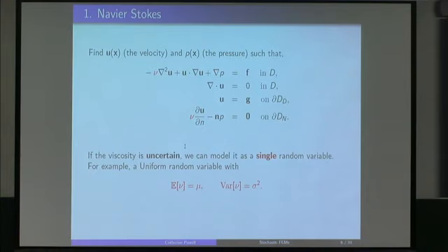Okay, so inside this model, the solution is a velocity and a pressure. But inside this model, this thing I've highlighted in red here is called the viscosity. In fluid flow modeling, this is really important because this affects the Reynolds number of the flow, the dynamical properties of flow, whether you get bifurcations, instabilities, and so on. That depends on the Reynolds number.